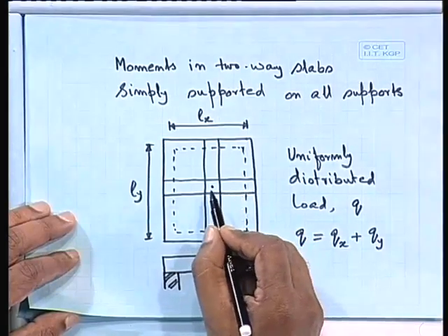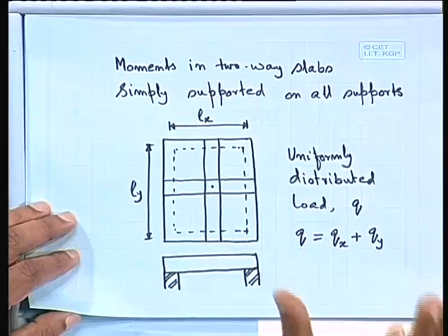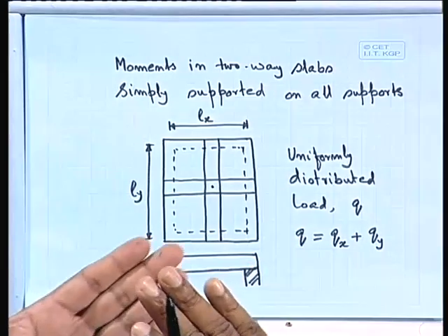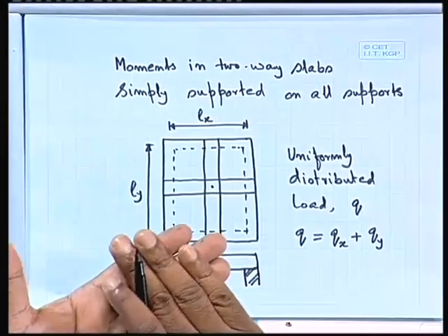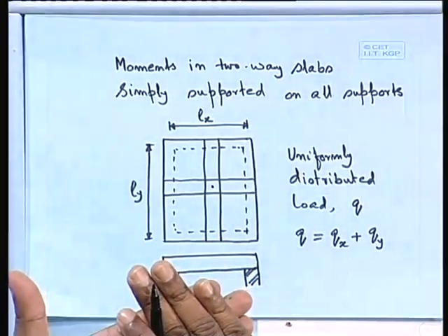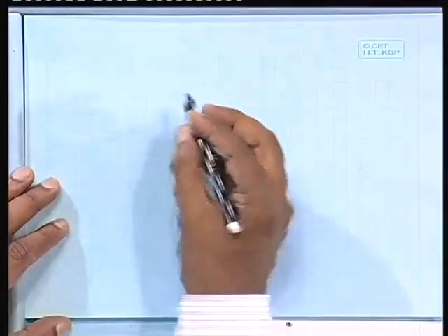We can take Qx and Qy, and on that basis consider the vertical deflection due to Qx and the vertical deflection due to Qy. Those should be equal because there is no differentiation; both of them deform at the same time and there is no disconnection. So we can take the vertical displacement as the same. That is our assumption. So, we can write down